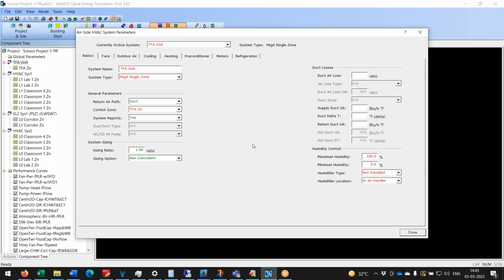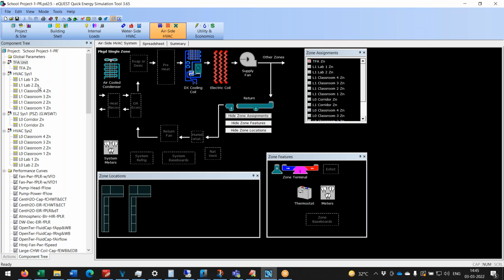No, condenser will... Sorry, hang on. See, this is the outdoor unit. I'm talking about our VRF system, not a chilled water system. Here also the outdoor unit will be holding the condenser, right? Yes, it's a condenser, but the condenser is sized less because not all of them hit at once. Then its TR should be high.